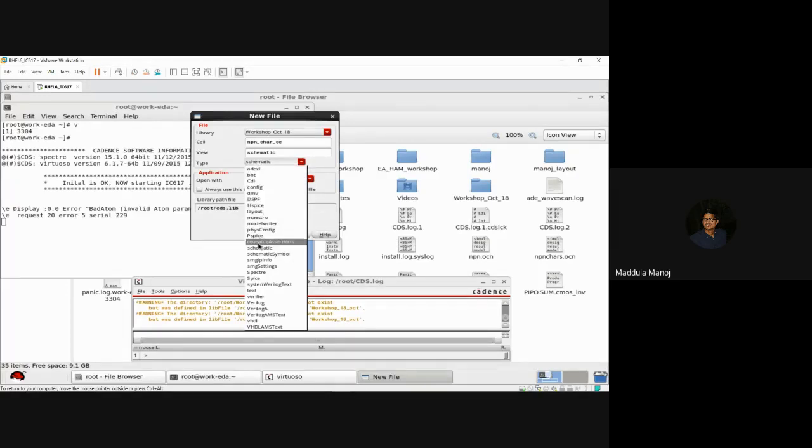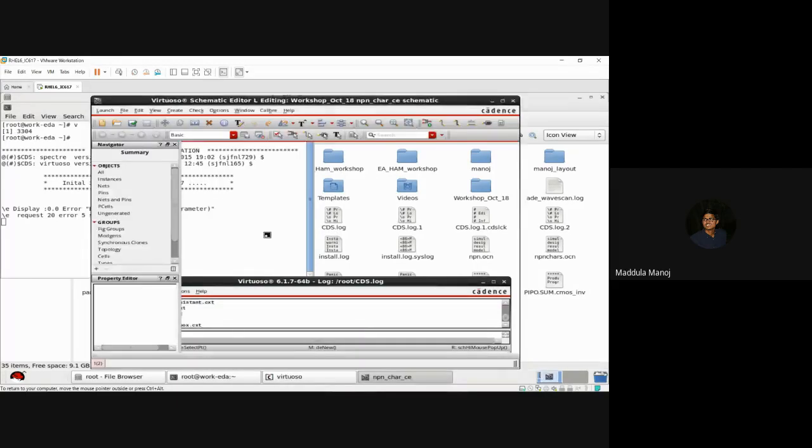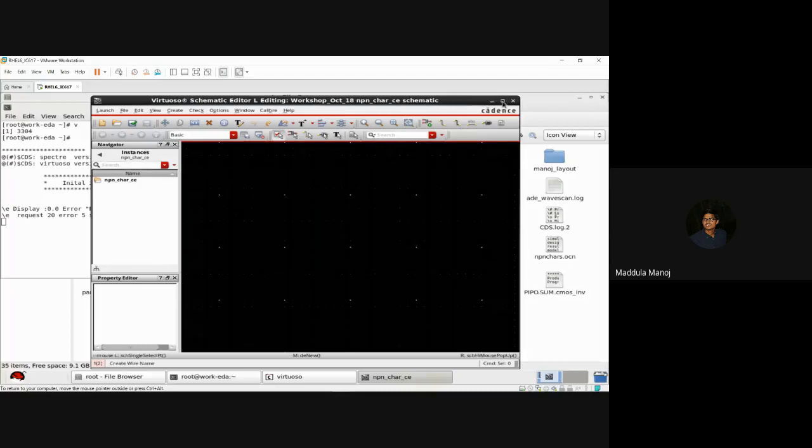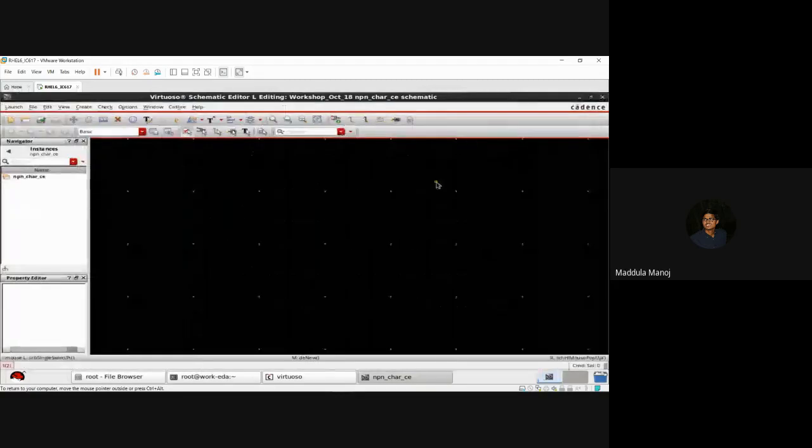After schematic in the design, we generally go to layout, which is where we lay out the circuits. We are not going to see that now. So first, as of now, just check whether schematic is the default. It will be schematic, so just check whether this is fine or not. Then click on OK. Then a new cell view is created and a tab is opened, which is an empty tab where we need to place our circuit.